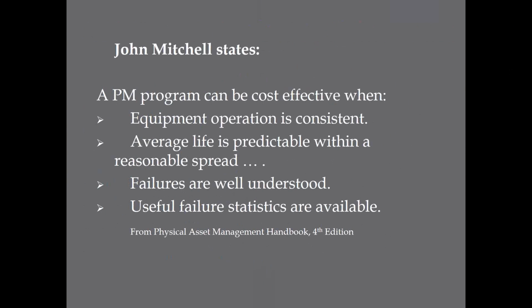What about the failures? One of the classes I do in plants for operators and maintenance is equipment failure modes. Once an operator or maintenance person understands how a piece of equipment can fail, they can make their PMs more effective. An example would be I do a webinar and I do training at plants called the 50 failure modes of electric motors. Understand there's 50 different ways an electric motor can fail. If you understand all those ways it can fail, it's a lot easier, a lot more beneficial to do the inspection. What if you have useful statistics? What if you're keeping track of mean time between failure? Those are useful statistics that help us develop time frequencies for PM.